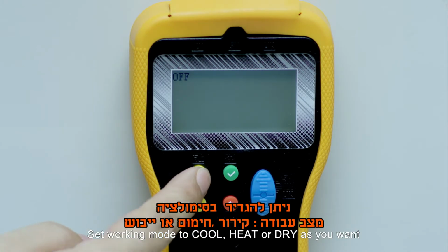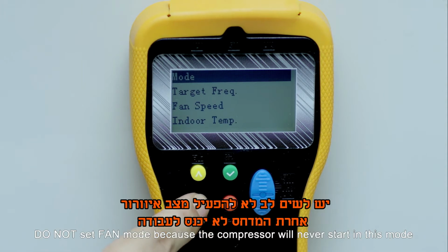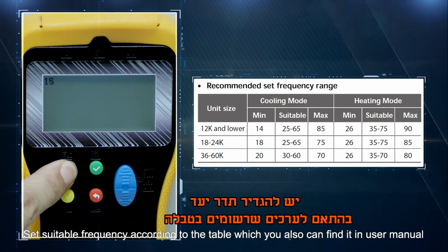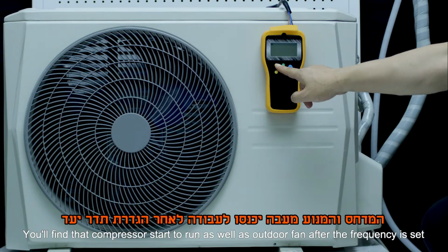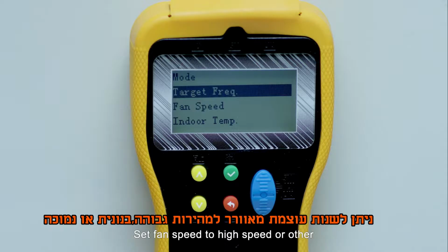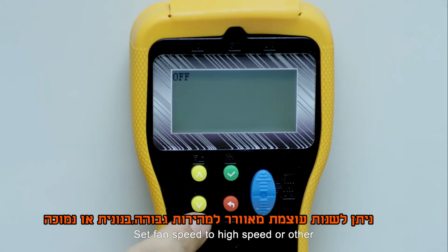Set working mode to cool, heat, or dry as you want. Do not set fan mode because the compressor will never start in this mode. Set suitable frequency according to the table, which you can also find in User Manual. You'll also find that compressors start to run as well as outdoor fan after the frequency is set. Set fan speed to high speed or other.